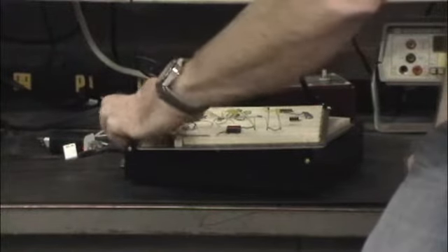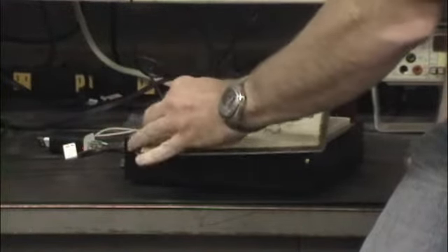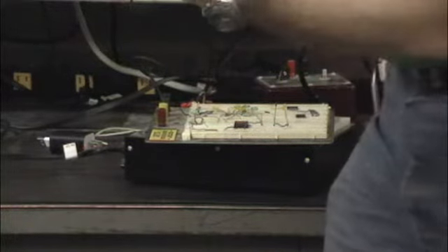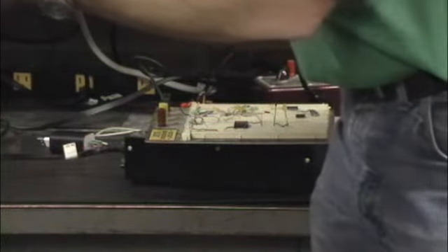Oh, capacitors. See this one? This is an electrolytic can. So I talked about last week, some capacitors care which way you line it up. Notice the gray stripe has the minuses on it. That's the negative side. That goes to ground. If you connect it up wrong, it can literally blow up. In fact, if you see the little cross on the top, little indentations that make the cross, that's a blowout valve. So if you overheat it, that'll blow out and actually explode, so it explodes up in a way.